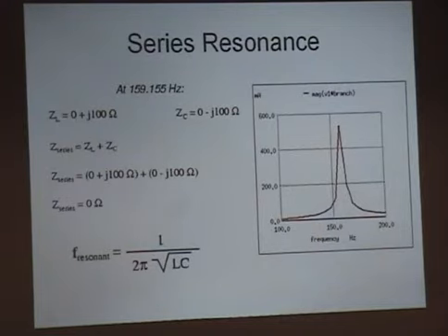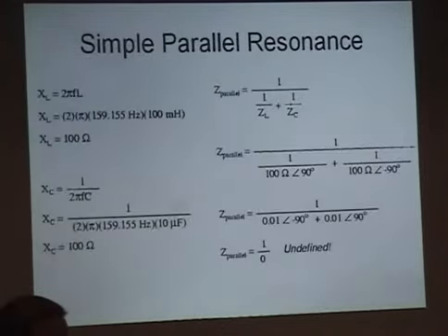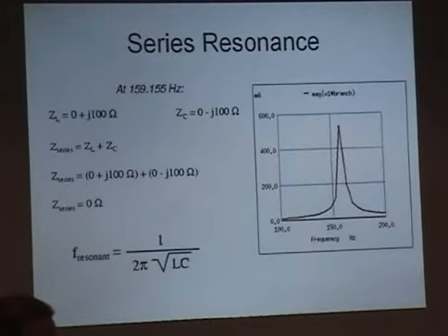An antenna tuner is the same thing, only on the output. It can look the exact same way, and you're just trying to pick certain things to get through. Tank circuits stabilize oscillation. You can use them for filters or antenna tuners. In the next class, we are going to go through LC tuners, pi tuners, and Z-match tuners. Do you know what a Z-match tuner is? Well, sounds like impedance matching. Well, they're all impedance matching, but this one allows me to vary inductance by having two variable capacitors. So it's an LC that has two. It's an LC2.